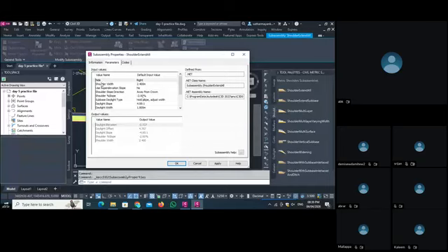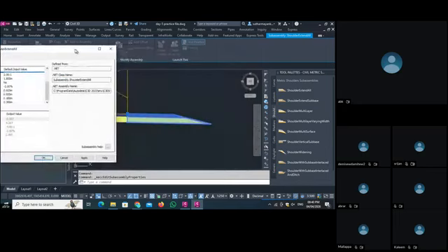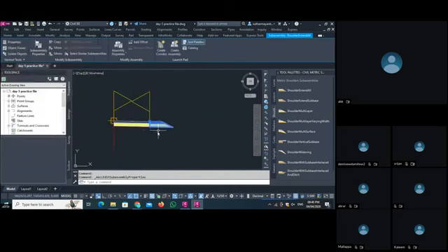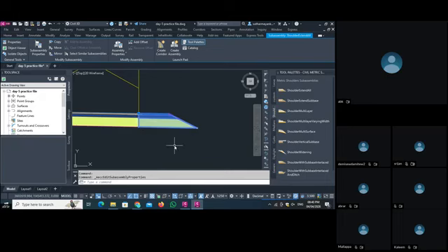If you want to change this to one, you can select one, and the daylight slope we can give as 2. The rest we are not changing. Then if I apply, the width is automatically changed. So remember all the values we have given. The shoulder width is 1 meter now.